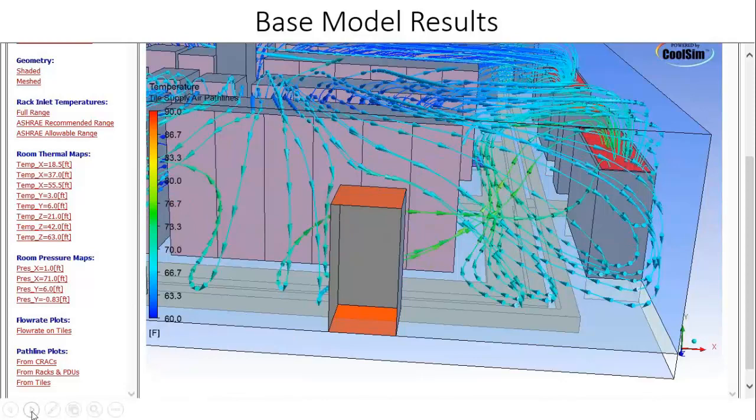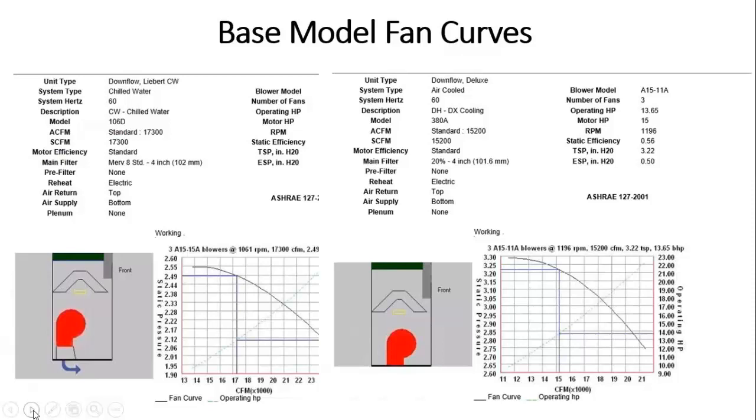And again, I like to use CFD models to make those simulations and predictions. Now, in contrast, one thing I wanted to point out here is the fan curves. A lot of folks will also say, well, do you have enough pressure? If you got too much clutter under the floor, then the fan isn't going to be able to blow at its rated CFM. It's not going to be able to deliver the mass airflow at its rated CFM because you got so much pressure across the fan it won't work. So in this case, we are running with fan curves on, and it's working fine.